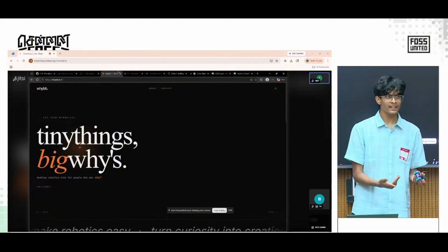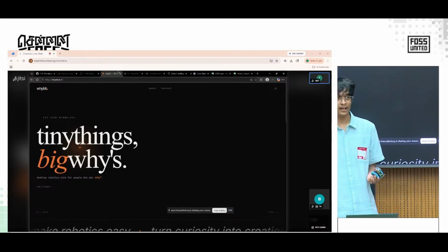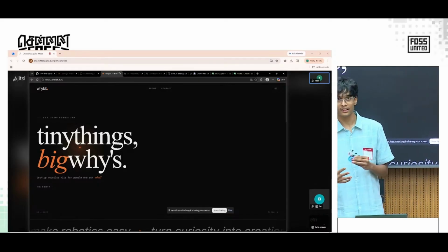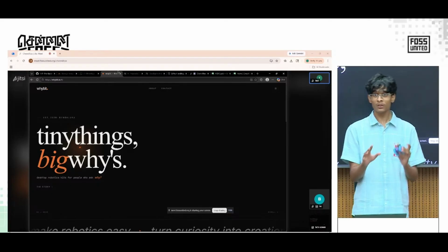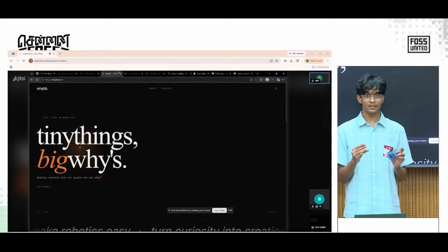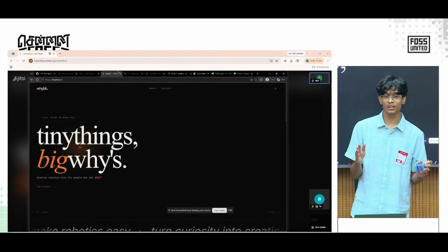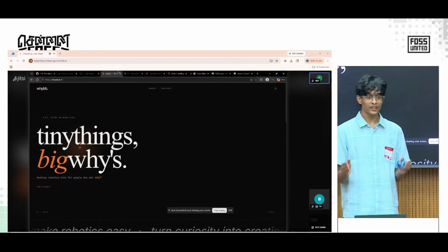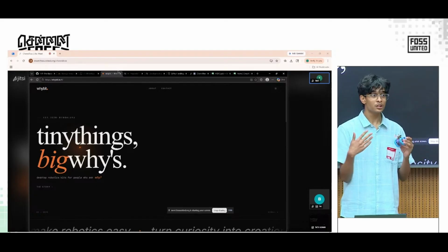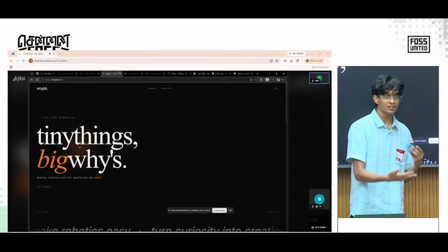So what I did is I bought a normal 180-degree servo motor, and I opened it up and modified it to make it 360 degrees. What a servo motor is actually used for is actuators and many other applications, but it can only perform for a set angle. You give it an angle and it goes to that angle. But you want it to be continuously moving. For something like this, you want the tank to be continuously moving.